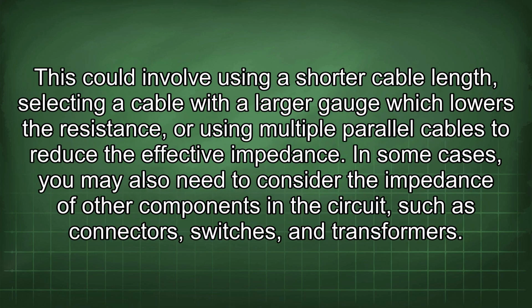If the calculated impedance exceeds this value, you need to take steps to reduce it. This could involve using a shorter cable length, selecting a cable with a larger gauge which lowers the resistance, or using multiple parallel cables to reduce the effective impedance.